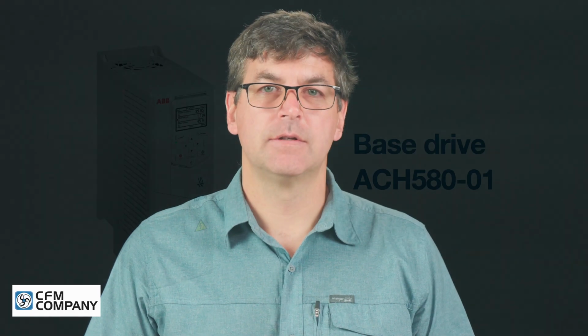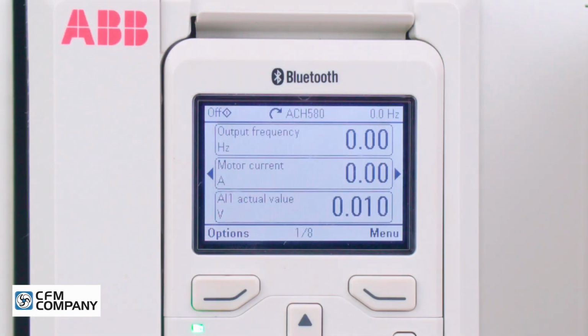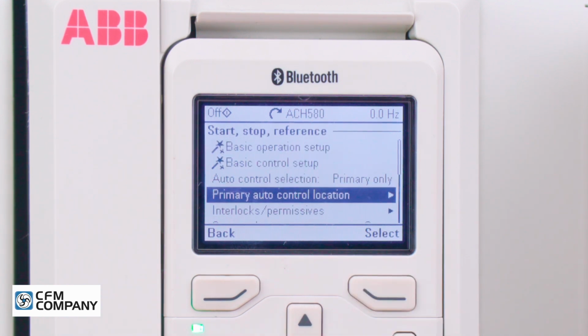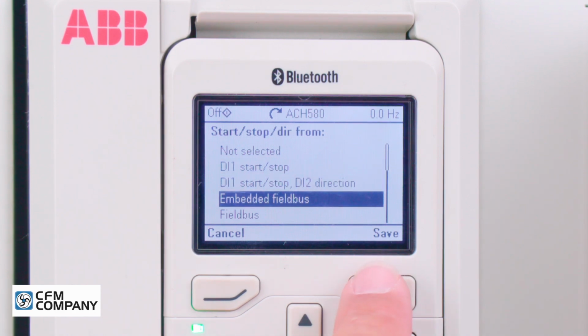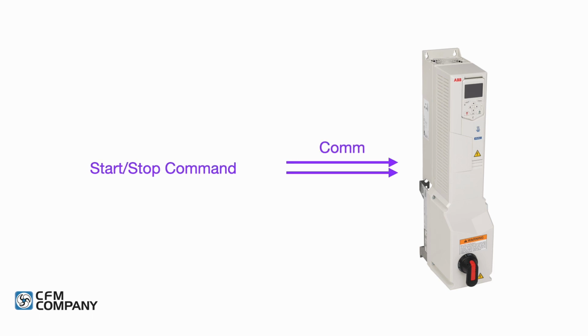The start-stop command can be sent over serial communications. On an ACH580 drive without an Eclipse bypass, press Menu on the control panel. Select Primary Settings. Select Start-Stop Reference. Select Primary Auto Control Location. Select Start-Stop Direction From. Select Embedded Field Bus and press Save. The drive is now programmed to receive a start-stop command using the embedded field bus, EFB.